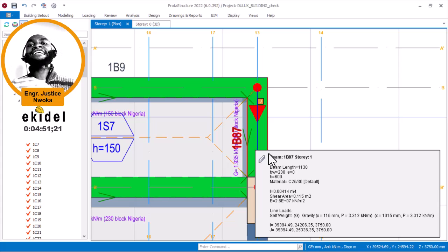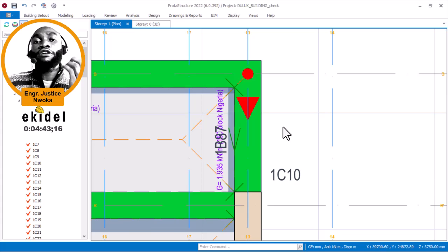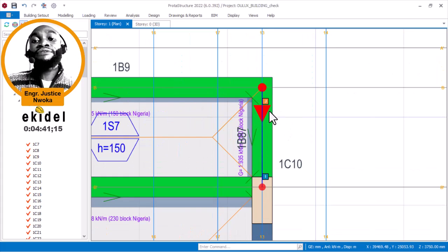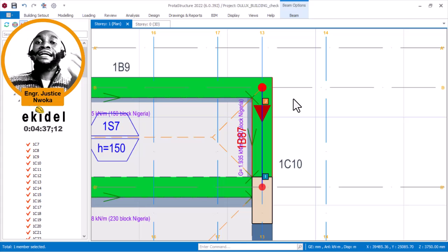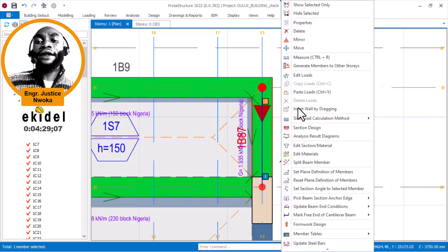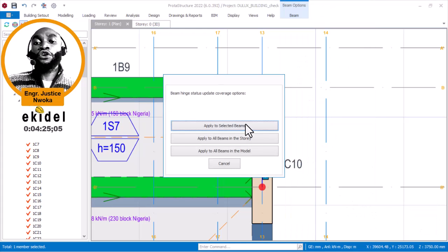So it requires a top reinforcement to be able to withstand the point load and all that. So cantilevers always have very high top reinforcement. So don't ever hinge, apply a pin end, on a cantilever. That is the worst thing you can ever do in your life as a structural engineer. Okay, that's fine.